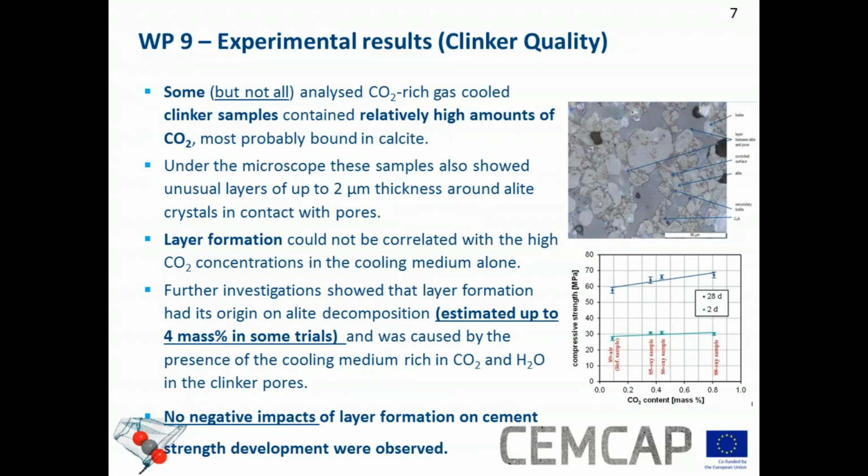We also have some, well, here I'm showing you the experimental results regarding clinker quality. Some, but not all, analyzed CO2-rich gas-cooled clinker samples contain relatively high amounts of CO2, most probably bound in calcite. I would like to underline here that only some of the samples showed this effect, not all. I will explain in a minute why this is so important.